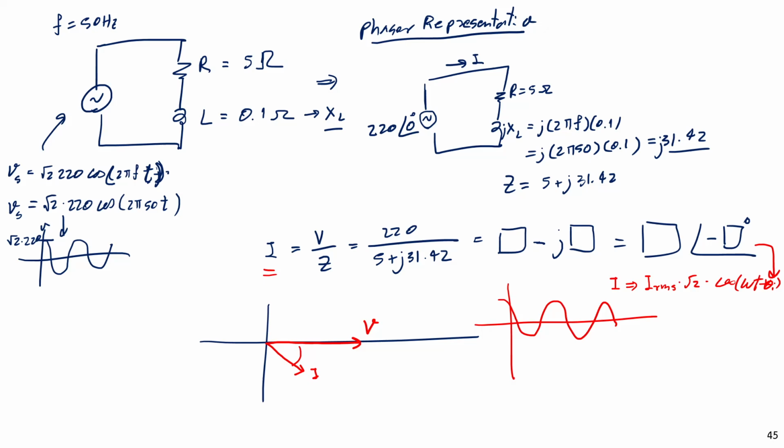So with this method, we can calculate the sinusoid waveform using complex numbers, right? Just transform everything into the RMS value, and the inductance and capacitance will be represented by the reactance value, XL.